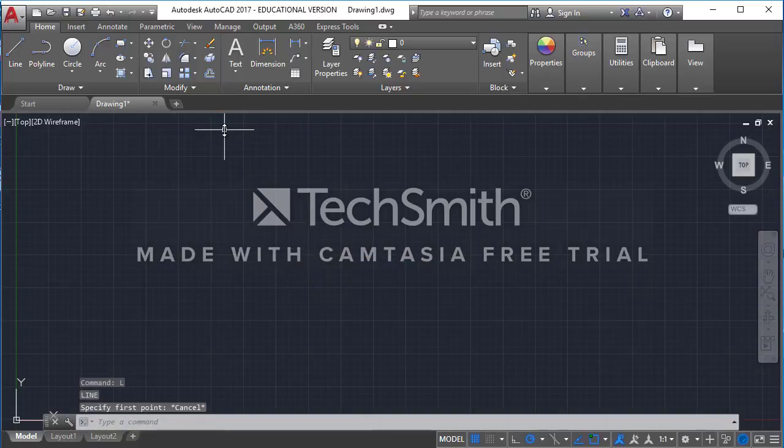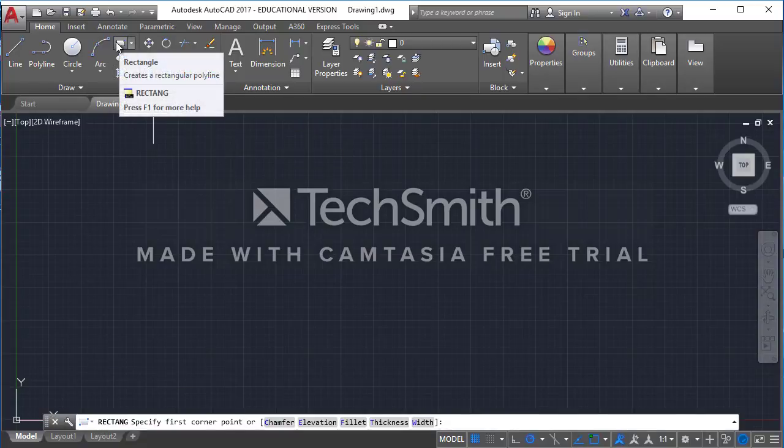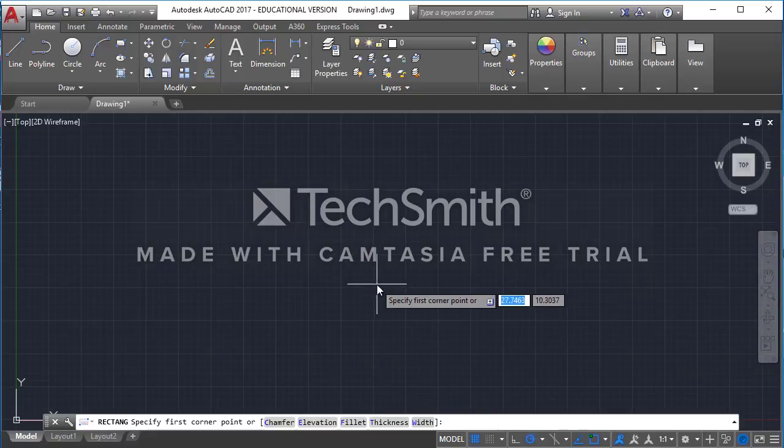Some commands, like if I type in ARC, give you other options here. I can type in C for center. I'm trying to find another one. Right here, when I click on rectangle, notice that it also gives me several other options on how I obtain my rectangle. We'll talk about a handful of these, but for the most part, you'll probably need to experiment on your own to see what some of those do. It tells you that you can create a chamfered rectangle, an elevation rectangle, a fillet rectangle. More later about what those mean.